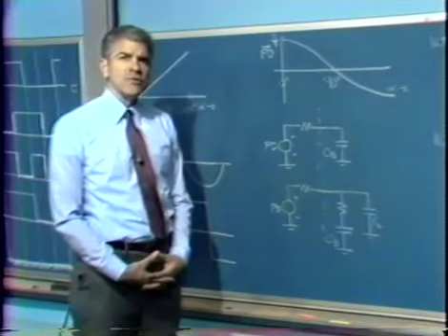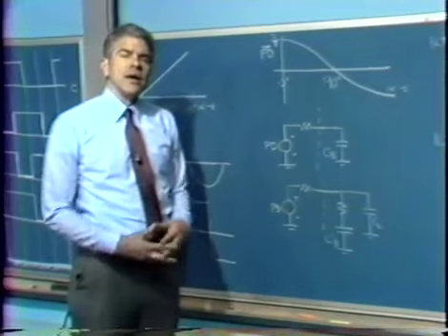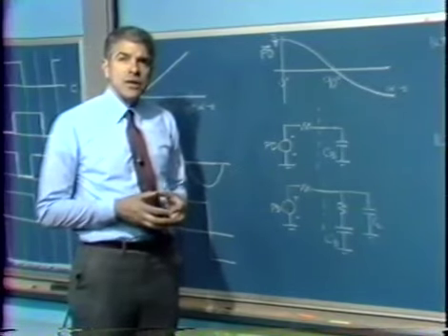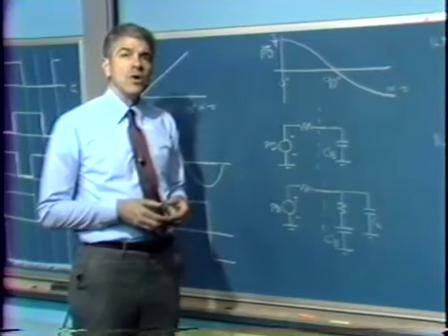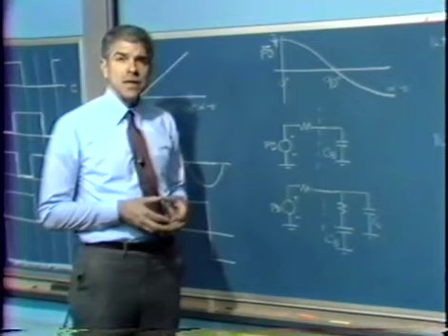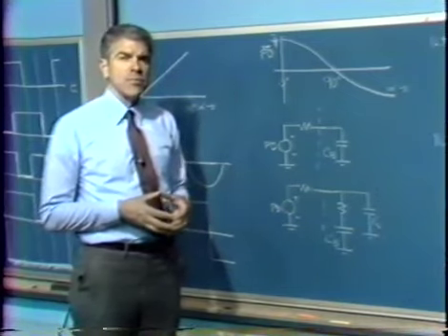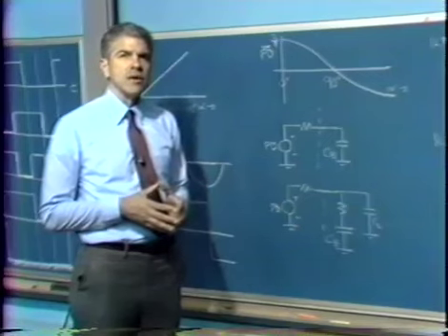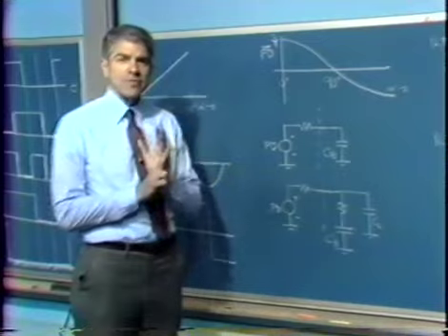If we have one more integration following the phase detector, and if we can stabilize the loop, the additional integration would tell us that under static conditions, when the signals are time invariant, the loop will work to drive the signal out of the phase detector to 0, or to its operating point, exactly to its operating point. So we'll end up with a system that has 0 relative phase error, whatever the operating point is.